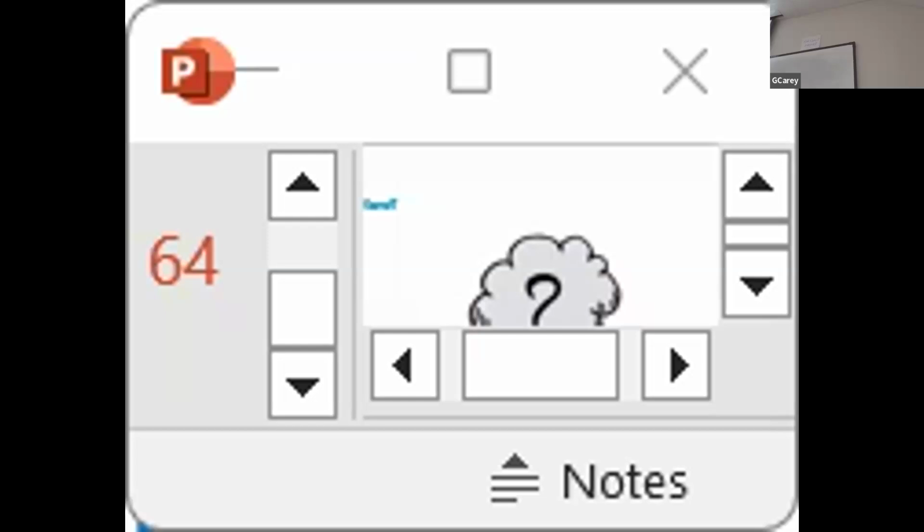And typically, like last week when we were talking about pump curves, we'd have different impeller diameters. What we're showing here is different speed curves instead of the impeller diameter. It's the same fixed impeller. I'm just changing the speed. And as I change it, I'm changing it because of system conditions that are allowing me to do it. I can consume less horsepower and require less horsepower to move the 50 gallons a minute because the pressure drop is so much less than at that design condition of 100 gallons a minute at 100 feet of head.